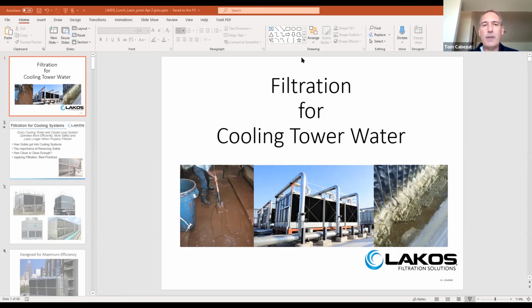The recovery vessel, you have maintenance. And so if you know that it's on a building where maintenance is going to be an issue, where guys aren't going to maintain it, I would probably lean towards doing the auto purge valve versus the recovery vessel. The bags act as kind of a secondary filter. You can size them for 25 microns or 50 microns, or we can even go finer if you want to, but they will plug up quicker.